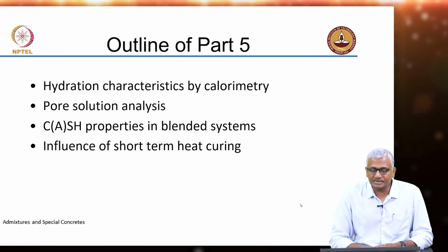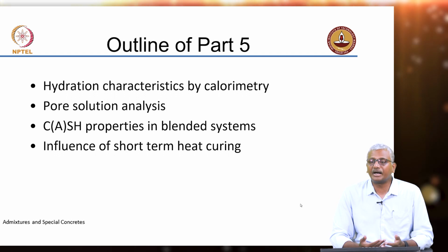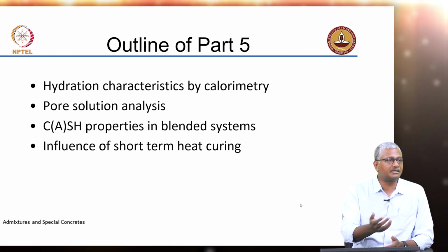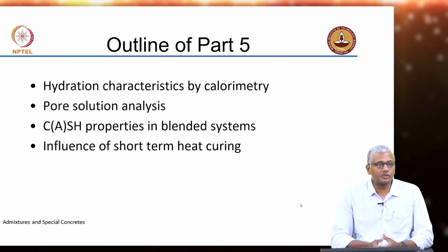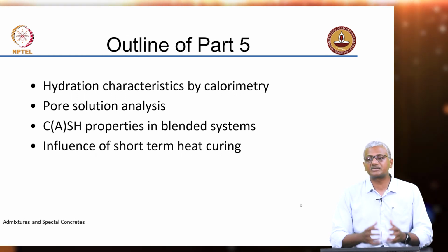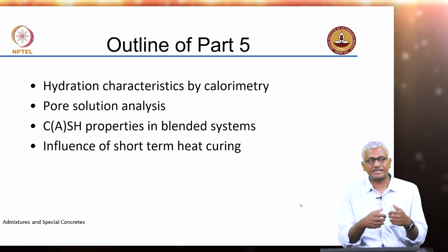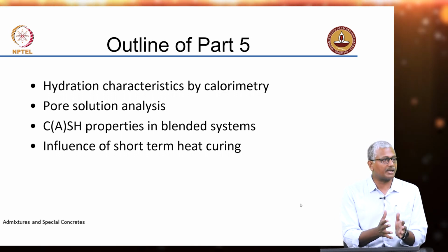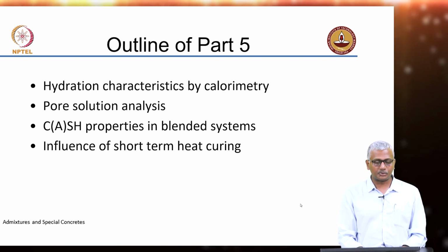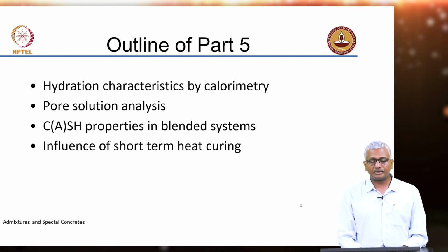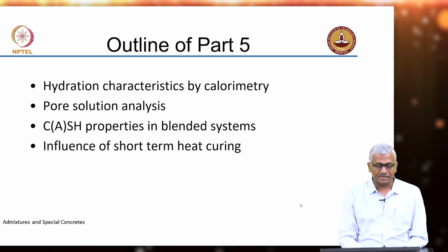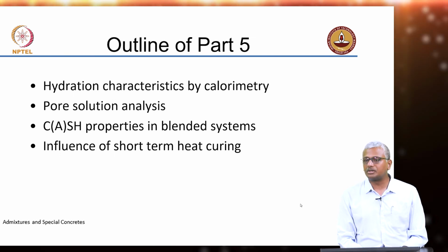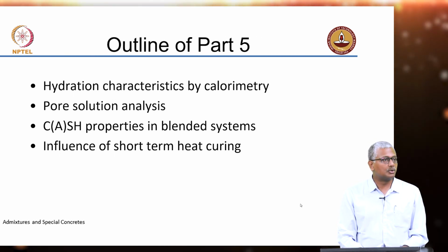So, in this part we will primarily look at how the hydration characteristics are seen with respect to calorimetry. We will look at some examples of pore solution analysis. When you extract pore solution from a concrete which has cement replaced with mineral additives, what does the composition of the pore solution look like? The calcium silicate or calcium aluminosilicate hydrate properties in blended systems, and some examples of short term heat curing and what it does to the overall system.